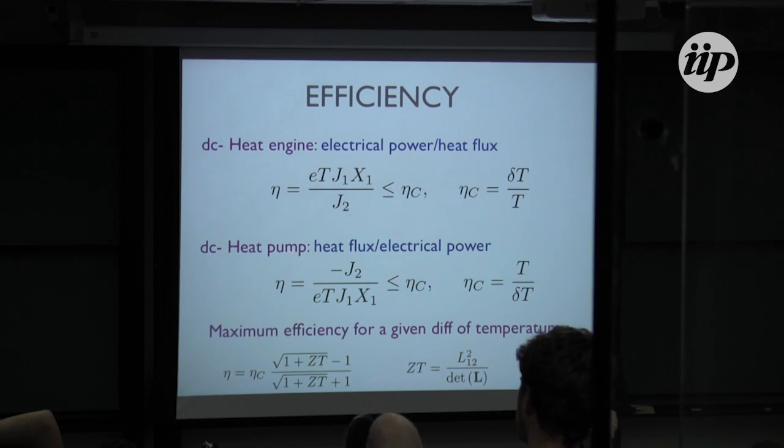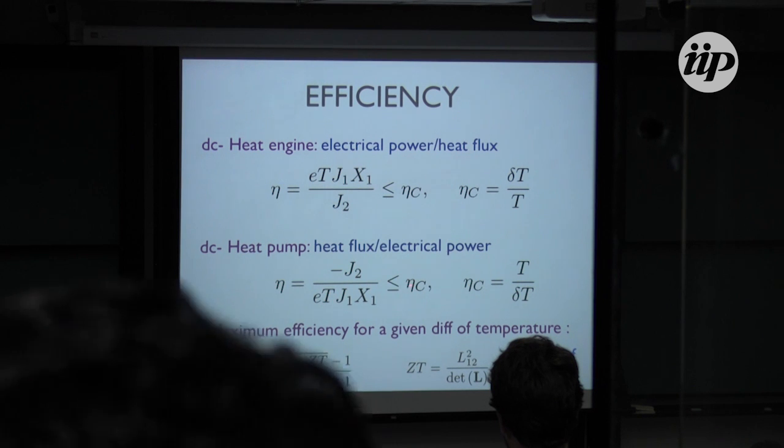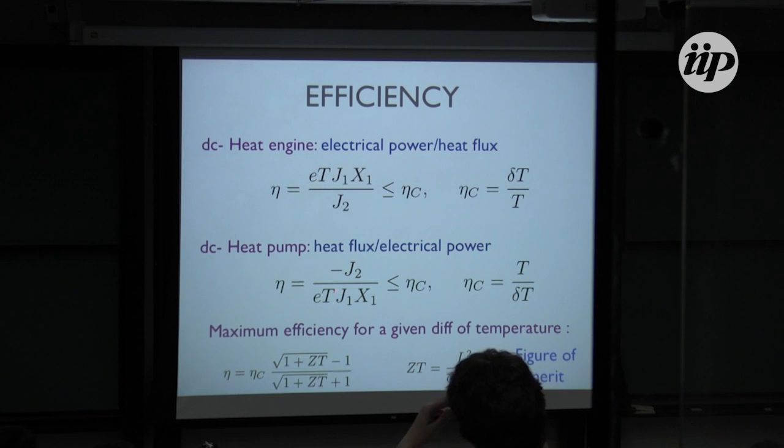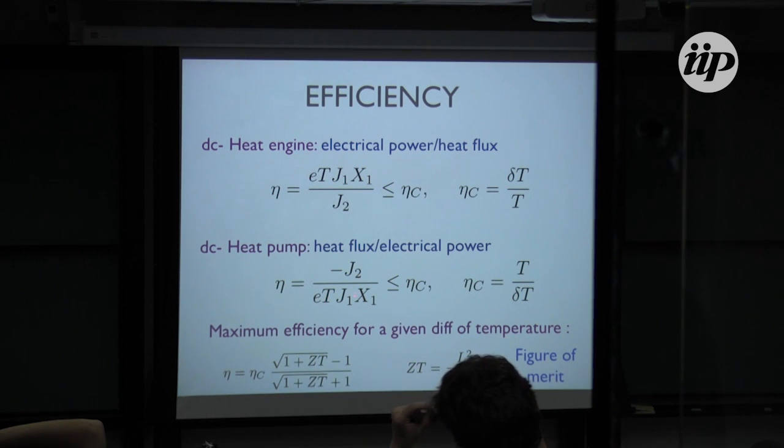For the case of the refrigerator or the heat pump, we have the other way around. We want to extract heat from the cold reservoir, and we have to inject electrical work. Again, this is bounded by the Carnot coefficient of performance.